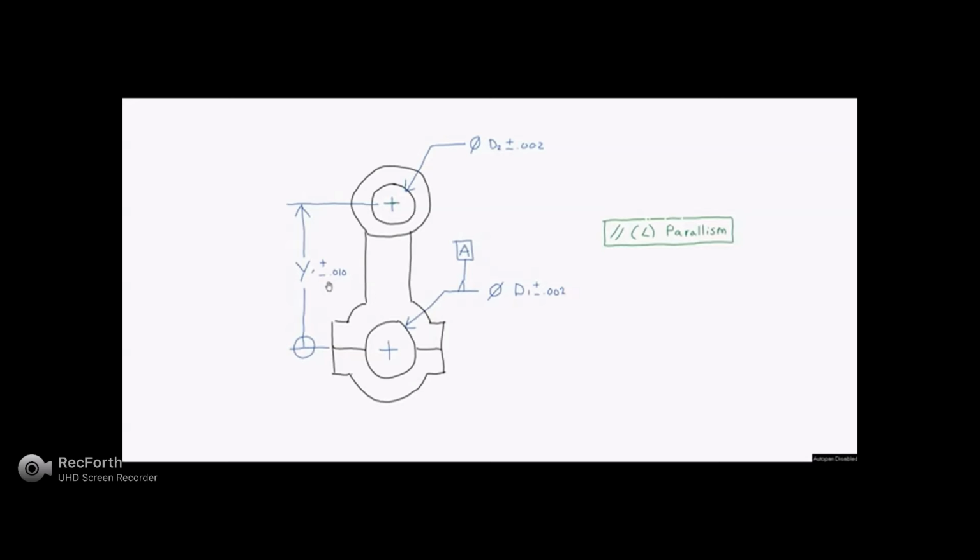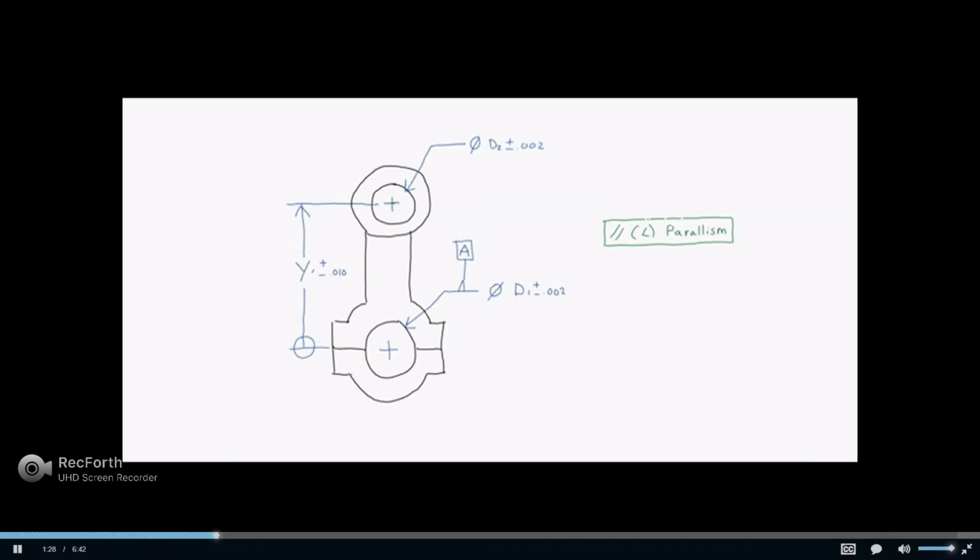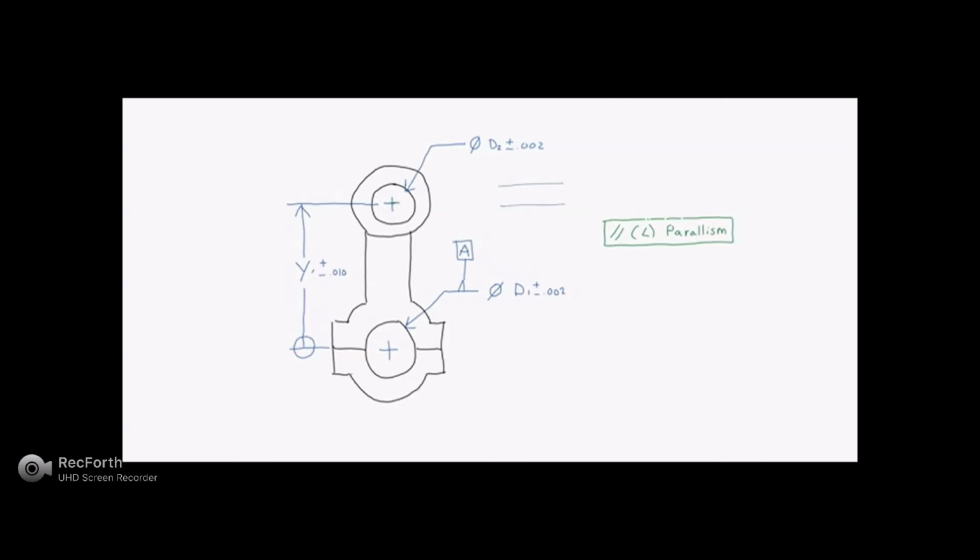So what that distance dimension does give us is two tolerance planes that are as deep into the screen, if you will, as our upper hole feature is long, and this allows our as-built hole feature to perhaps start at the closest distance and then tilt away from our lower diameter D sub 1 by up to that plus or minus 10, which is a total worst case parallelism of 20 thousandths.